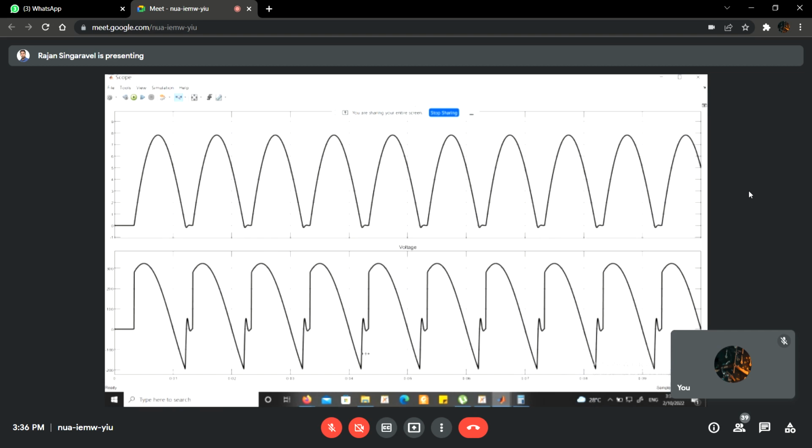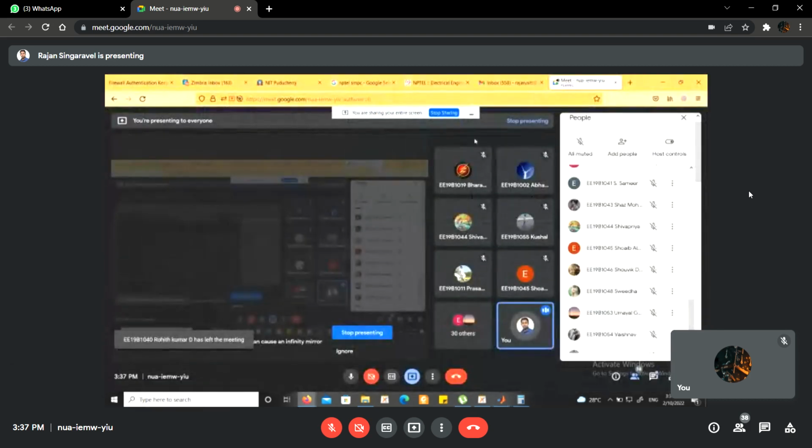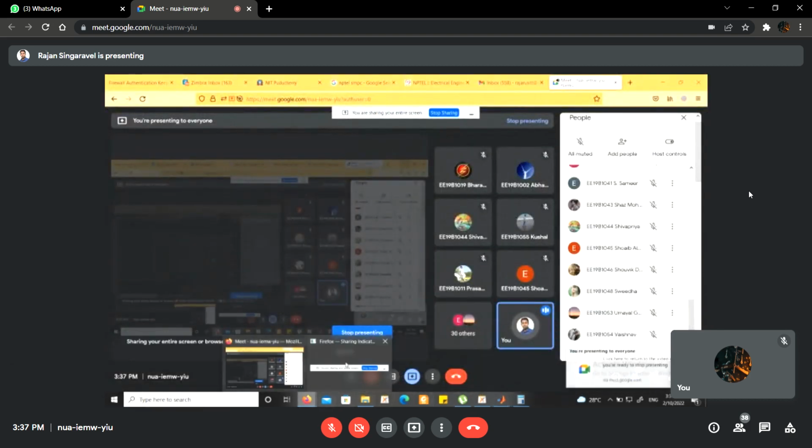There is no problem with that. This is the nature, and to be very clear, we will not subject this alternating voltage to the load terminal, and we will have a capacitor. We will filter this out, and we should try to supply a pure DC for the load, right? And this is because of the non-idealities in the circuit.